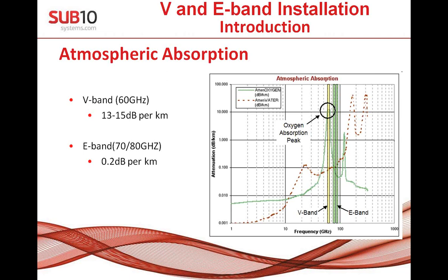The second option is TDD, which is time division duplex, when you are sharing one channel and systems are changing or sharing this frequency based on time. In this case, if I compare our gigabit FDD system with a TDD system, it's like a 2 gigabit system, because in TDD, if somebody is quoting capacity, it's calculated as downlink plus uplink, which is typical for a TDD system.